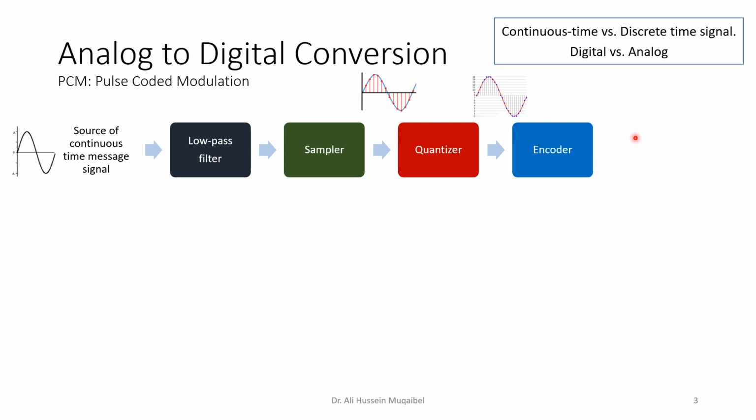Then we do encoding. Encoding will turn the signal into what we call a pulse coded modulation signal, which means the information is now modulated into pulses, usually represented by zeros and ones. We have the PCM signal, and we'll take the signal to the channel. Now, the pulses that we transmit, as you see here, as they travel through the channel, lose part of their energy. They get dispersed and change with time.